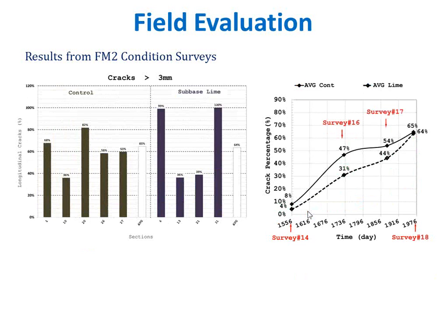For longitudinal cracks, and let me be fair, honestly, if we were to look at rutting depth or other measures of performance, that would not be the case. But for longitudinal cracks, this doesn't work. The hypothesis behind it is that essentially you are creating a stiffer, which is good, but more brittle material. And if what we're trying to minimize is initiation of cracks, brittle is not good. But that's a different battle.